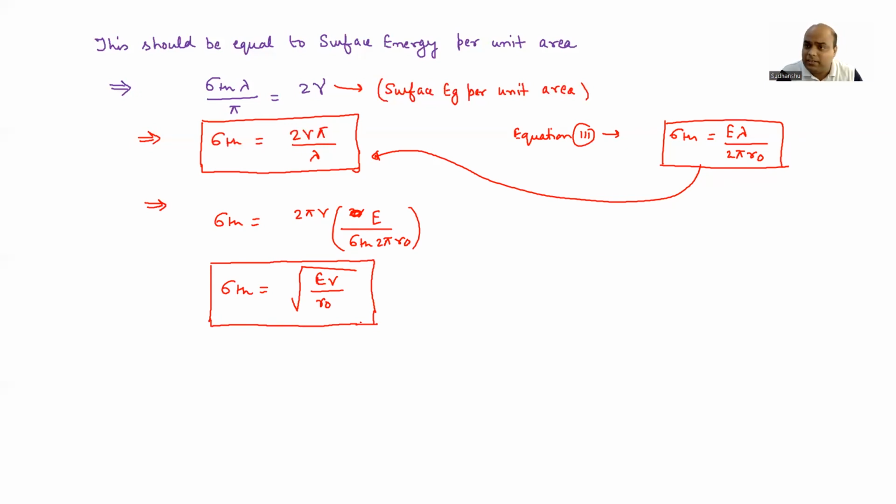Okay. So now let's compare these two and then realize the relative value of sigma th, and then you will see why there is a discrepancy. What we have observed in reality, when we do some experiment in the lab, and the theoretical strength values. So let's see some examples. So say you have copper, nickel, then NaCl, different materials, okay, including ceramics, silicon. Okay, so let's take five different materials, and then we have sigma th E by 2 pi we calculated,